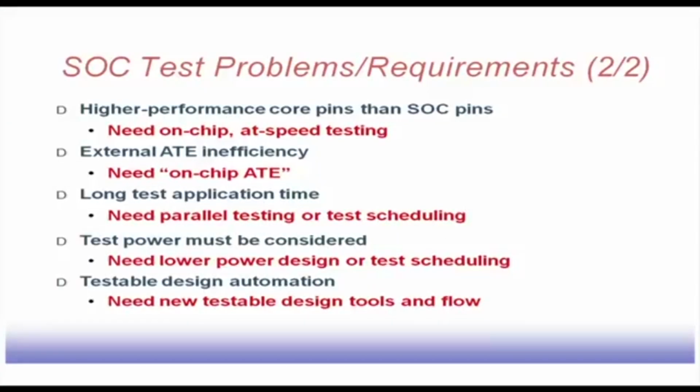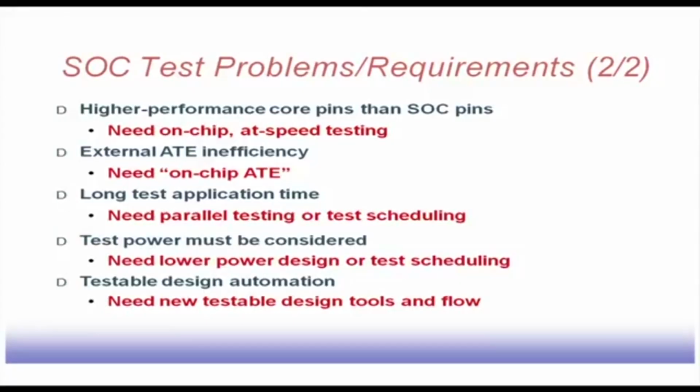But this test parallelism has its own problem as well, because test power is another important part. A number of modules being tested parallelly means a number of modules are going to consume power. As we have discussed previously, in normal mode of operation those modules may not be working simultaneously, but in the testing process, to reduce the test time, we have made all of them work together. So, of course, there is a necessity for high power consumption. It may be possible that all those power values are high, and as a result they consume a lot of power.